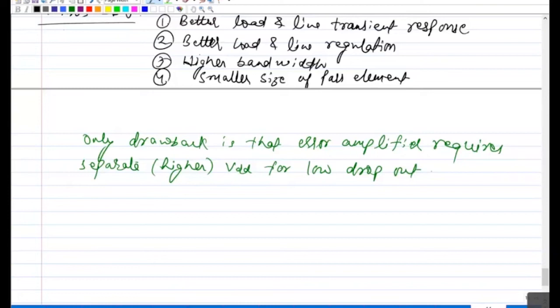So that's why NMOS LDO is most popular, especially in all low noise applications and those where you require very high PSRR, where your supply is a little bit noisy. And we know that when your LDOs are hooked up at the output of your switching regulators, there will always be a ripple on the input or VDD, and you need to suppress that. So for noise sensitive applications, let's say RF or biomedical applications, where even a 1 or 2 millivolt ripple at the output may not be acceptable, NMOS is a better choice over PMOS.